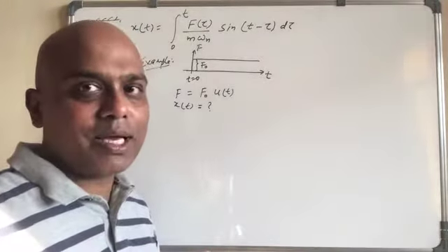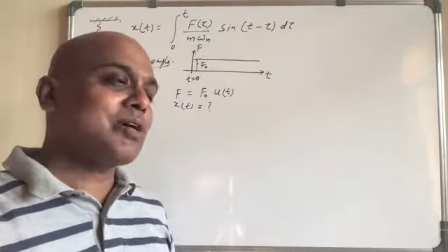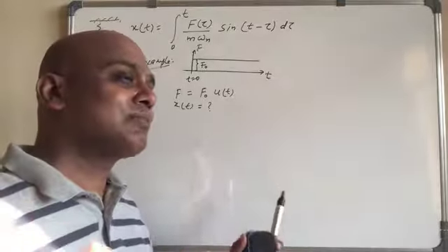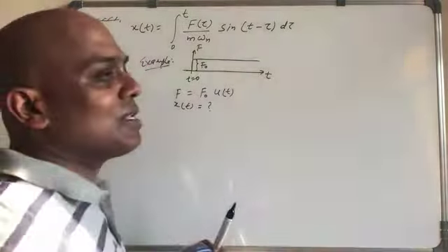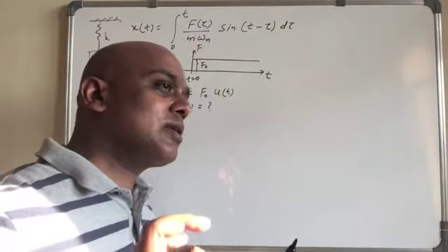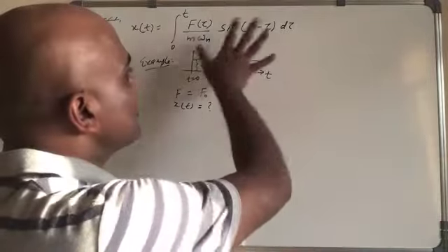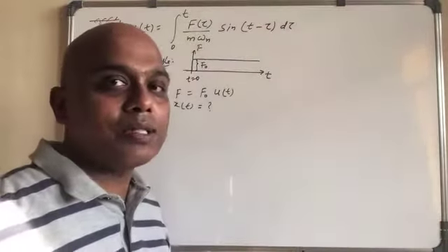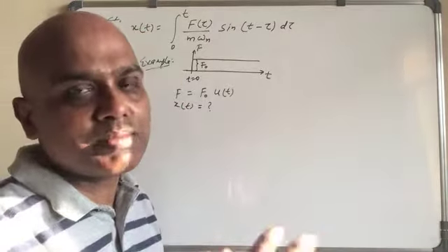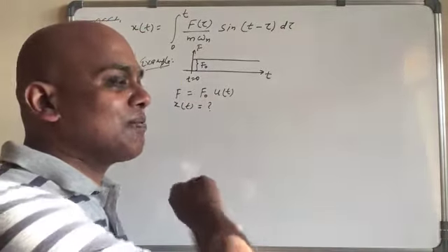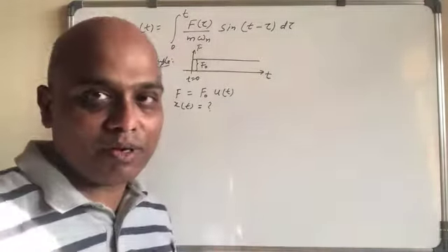Although it looks theoretical, let us say you have a big hammer, you strike the bridge, you record the displacement, and that is the solution for an impulse force. Then you can do convolution like this one to find the solution for any kind of input, whether sinusoidal, triangular, trapezoidal, or any kind of wave.